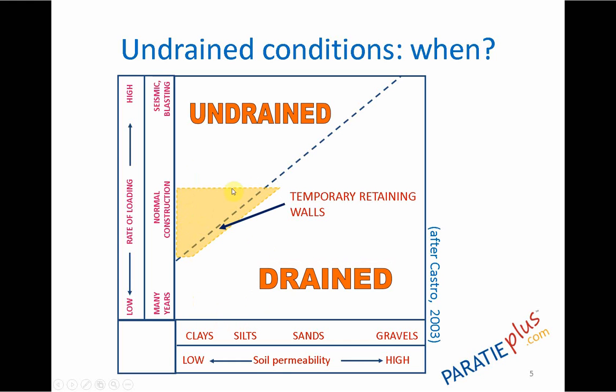Whereas, as long as the rate of deformation increases, for fine soils we may have initially undrained condition, whereas for sandy soils, drained conditions are applicable to normal construction times.